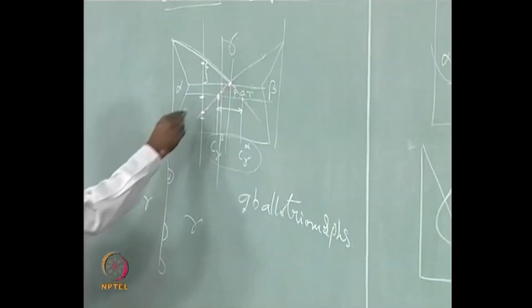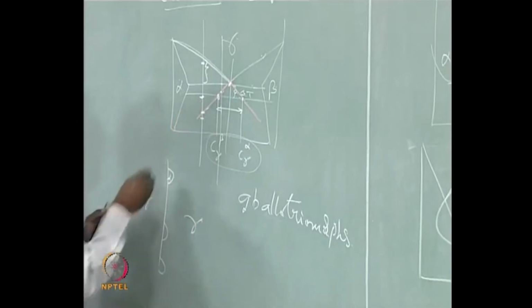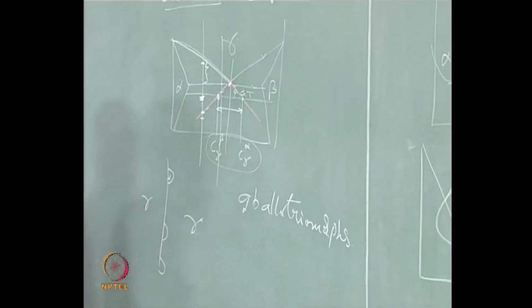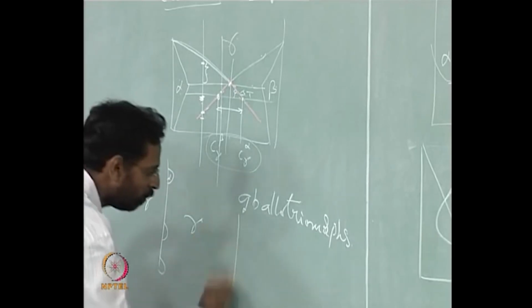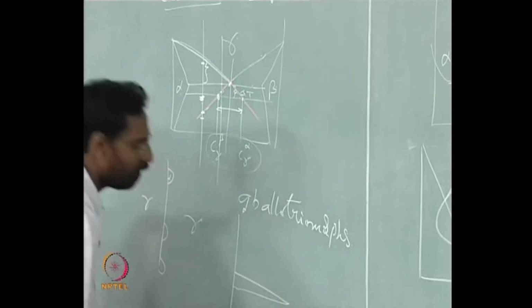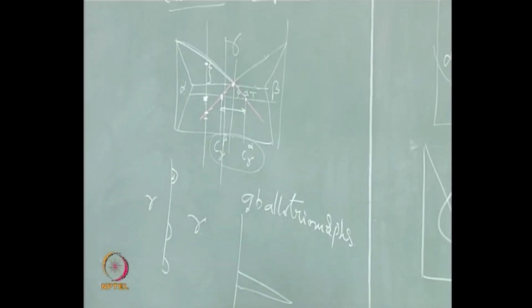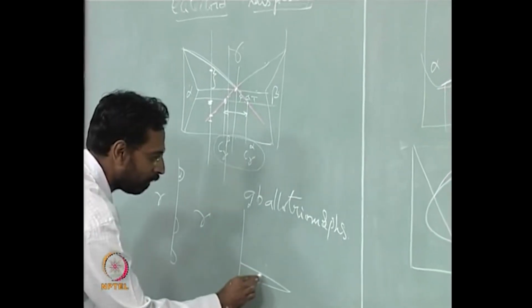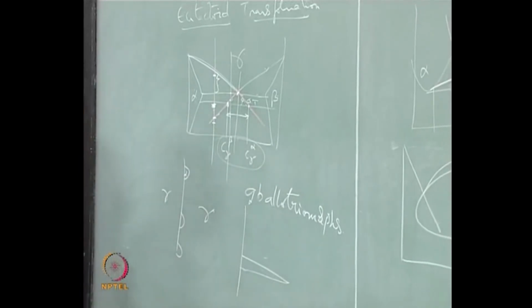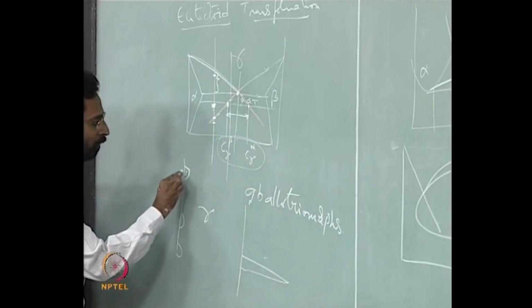The moment the undercooling is very high, and let us say somewhere here you see the alpha coming out, in such a case the alpha comes out as platelets with semi coherent interfaces, while here these are all incoherent interfaces.